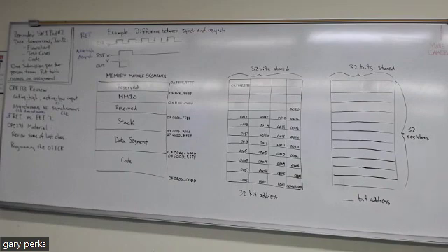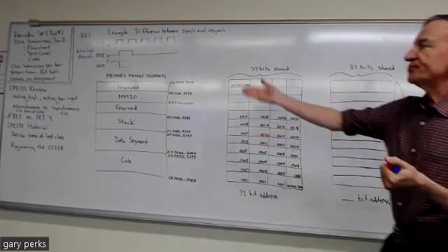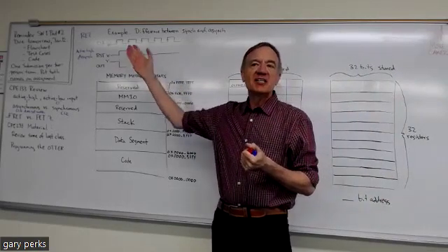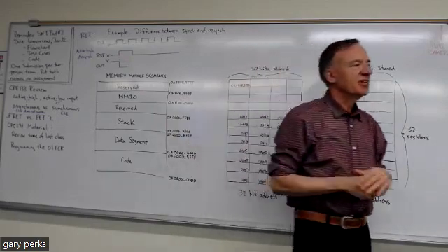That's something you want to avoid, right? Because if the change of the synchronous input is exactly at the time of that clock transition, flip a coin whether it's going to happen or not. So that's a good point, something you've got to watch out for because that can cause an ambiguous case.